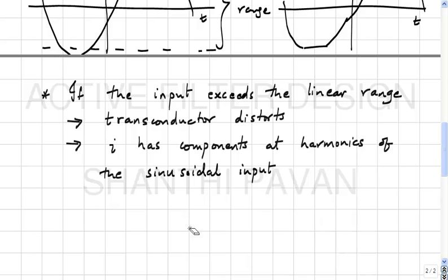So, this way we are all talking about the same thing when we say the linear range of this V to I converter is so many millivolts, so many volts. That is just a matter of notation, but all that I am emphasizing at this point is that every transconductor, depending on the way it is designed, is associated with a linear range, and if you want your filter not to screw things up, you want to make sure that the input to the transconductor never exceeds the linear range.